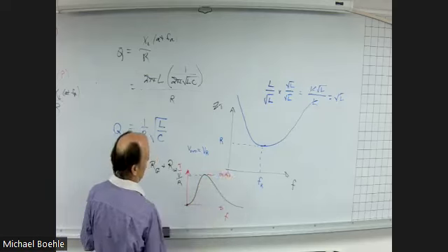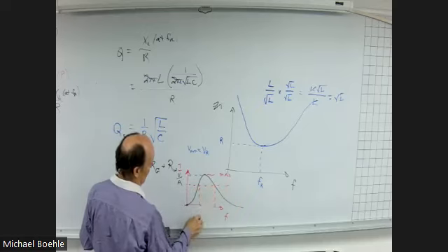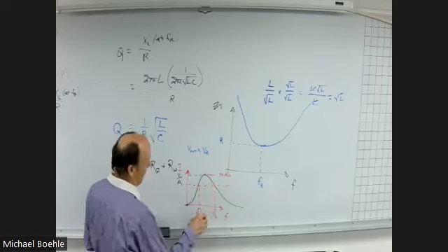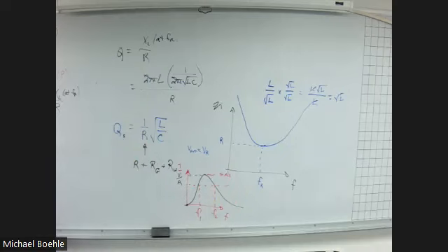Multiply by 0.707. You actually have two intersections, a lower and an upper cutoff frequency. This is a band pass filter. Band pass filter is achieved, built, whatever word you want to use, by looking at the voltage across the resistor versus the source.